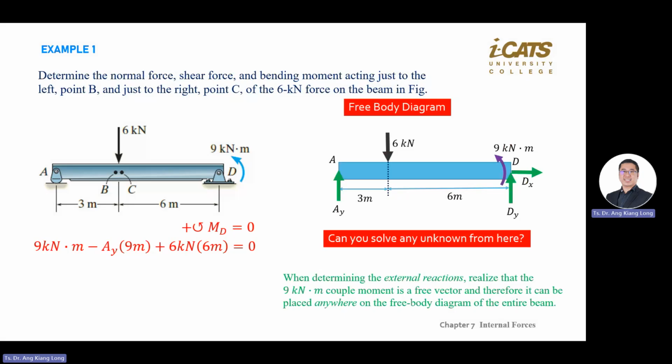So here I solve at point D. There's a trick there. When we solve sum of moment equals 0, anti-clockwise is positive. I personally recommend, if you see a diagram that has a lot of forces and moments, go to that point and find the moment at that point, then you cancel all those forces and moments already. That is the trick. Why do we find moment at D? Because once you put your finger at D, you cannot see the moment at this point, unless the external one.